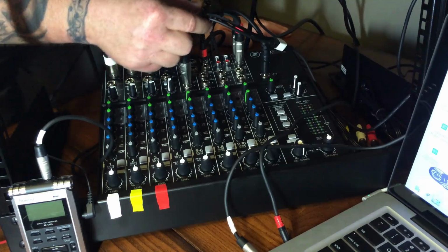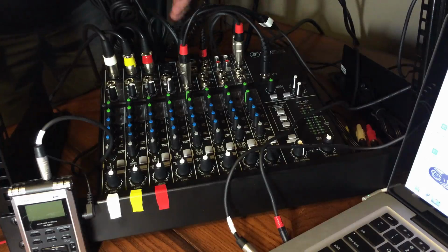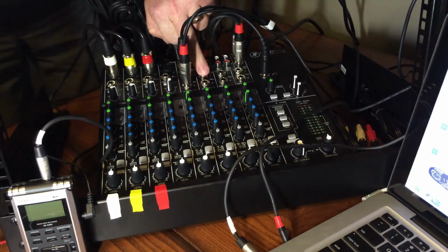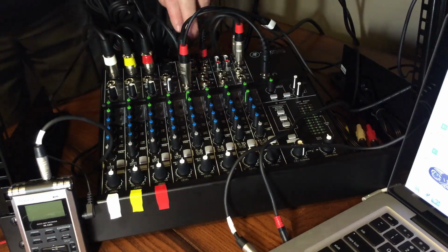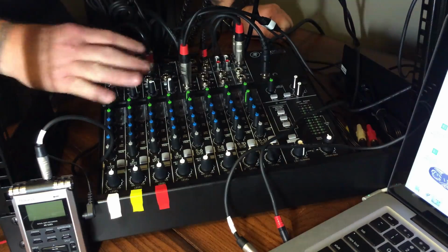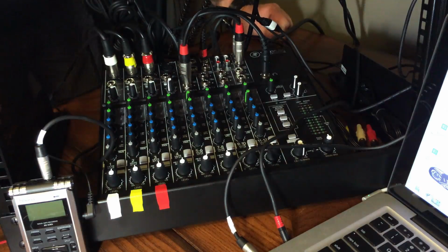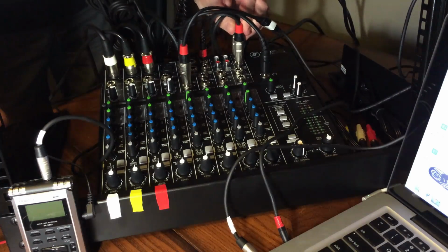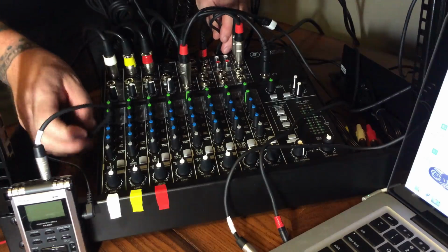So if I wanted to have that iPad input, I would just put it into another channel strip, which could be this channel strip right here. I would just hook my iPad the same way I hook my laptop in. I don't have it hooked in right now because I want to keep stuff out of the way for you guys, but that's how you could do another input. So we've got our mics, we've got our Skype input, we've got that all in the mix right now. I want that entire mix to go out to my external digital recorder. So I have these 1/4 inch dual TS into 1/8 inch TRS right here.